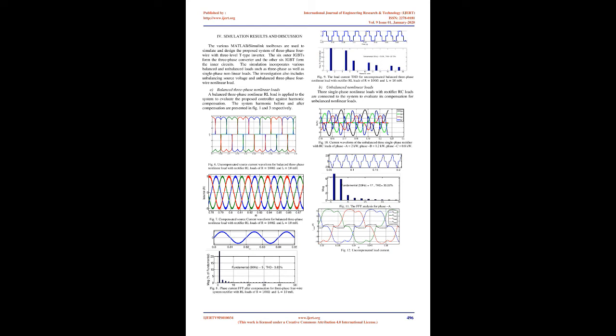The load currents of the three-phase nonlinear loads are composed of the fundamental active current, fundamental reactive current, and harmonic current. The active nonlinear load current and the active current of the converter are supplied by the AC source. When the SAPF control meets its goal, the load can be seen as resistive for the supply. Taking Im as the phase RMS current, the corresponding three-phase current can be written as follows.